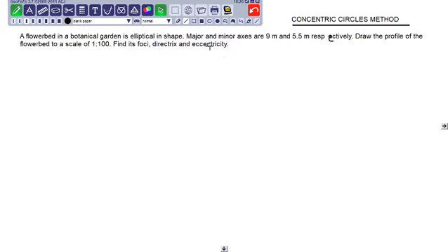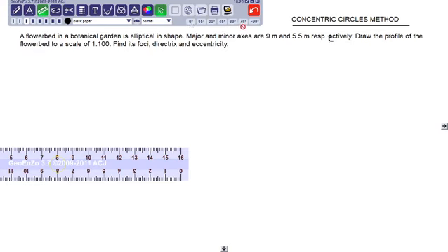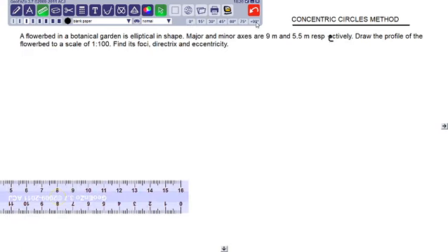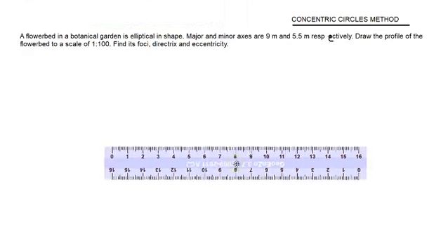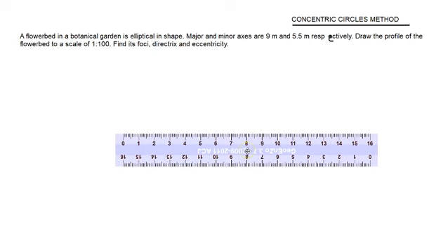Okay, so major axis is here 90 millimeter and minor axis is 55 millimeter. So what is to be done? First, let us draw the major axis. Since major axis distance is given to us, you can easily draw a major axis with the given distance. Let us say the major distance is 90 mm. So straightforward, take a distance of 90 mm.